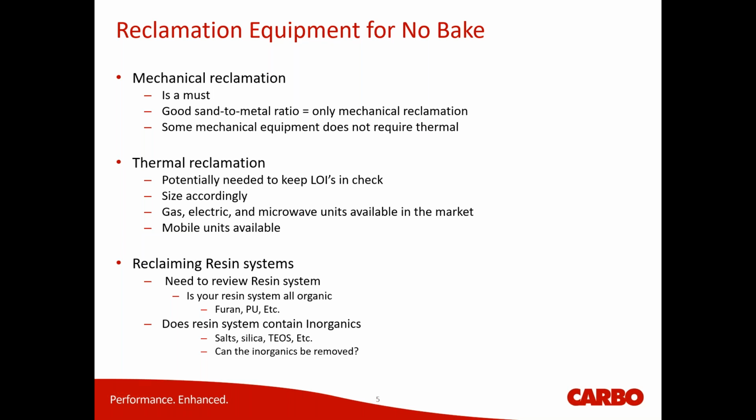You can counteract it with reclamation if you get the right reclamation system to handle it, or you can look at a different resin system. So basically, our discussion there about if you do have inorganics is you need to make sure you look at the right reclamation equipment to either get rid of it, or we need to talk about maybe doing a different resin system. Either one isn't a very good option.